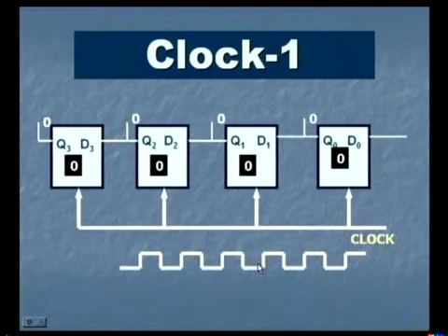On the first clock pulse, the first data bit will arrive. So, this is the first data bit serially fed into this flip-flop, and upon the clock pulse, that will be stored and the same is available as the output at this flip-flop. When the clock goes low, that will be available as the input for the next flip-flop. It is also ready as the output bit.